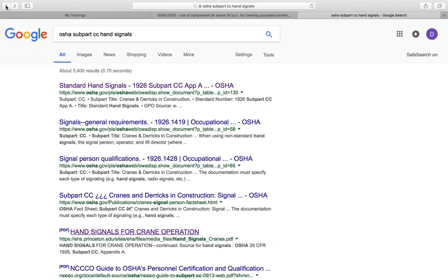So let's go ahead and move on to Module 7, page 15, which is Section 2. We'll talk a little bit about center of gravity and tipping points on these types of equipment. So what are we talking about, right? If you look in the green section of trade terms, center of gravity, what are we talking about? We're talking about the point around which the object's weight is evenly distributed, right? So that's that center of gravity. Keep it as balanced as possible in order to maximize the reduction of any hazards where that vessel or that vehicle might capsize, flip over, roll over, or whatever the case is.